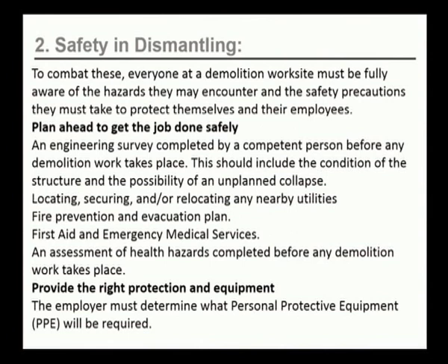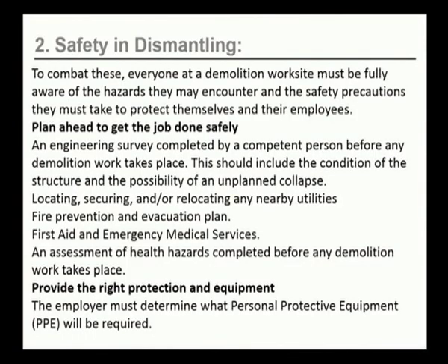To combat these, everyone at a demolition work site must be fully aware of the hazards they may encounter and the safety precautions they must take to protect themselves and their employees. The important principle is to plan ahead to get the job done safely. An engineering survey must be completed by a competent person before any demolition work takes place at site. This should include the condition of the structure and the possibility of an unplanned collapse.